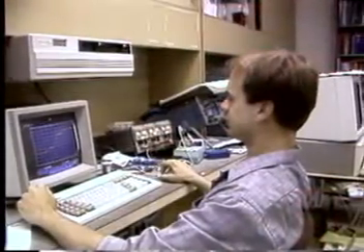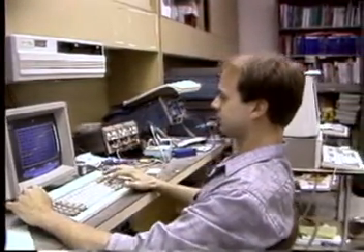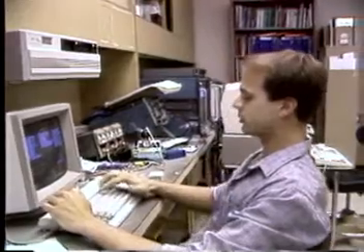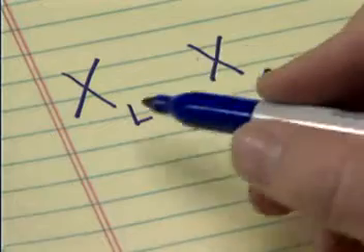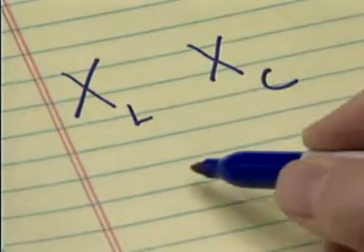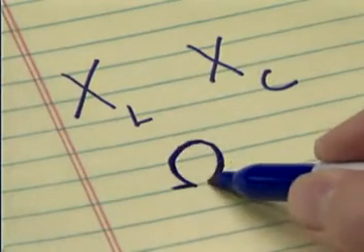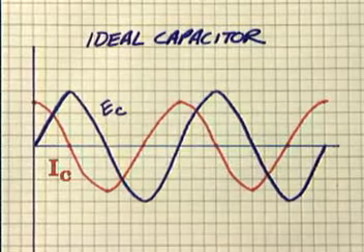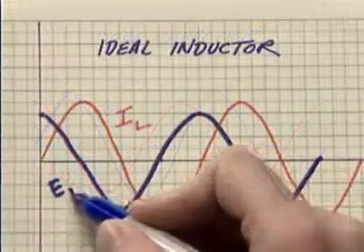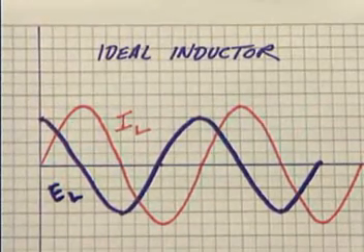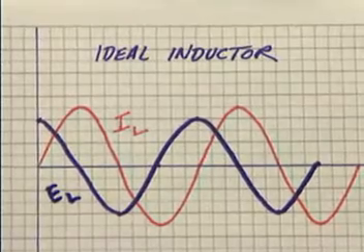It's important for you to have an understanding of these two types of reactance, because when you get to AC circuits, you'll see how reactance interacts with the circuit resistance in certain predictable ways, which become a critical factor in the design of circuits. For now, keep in mind that both inductive reactance and capacitive reactance are measured in ohms, and that in the capacitor, the capacitive current leads the voltage by 90 degrees, whereas with an inductor, the inductive current lags the voltage by 90 degrees.